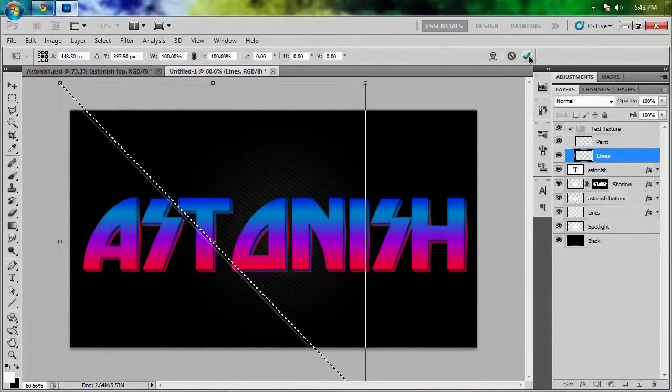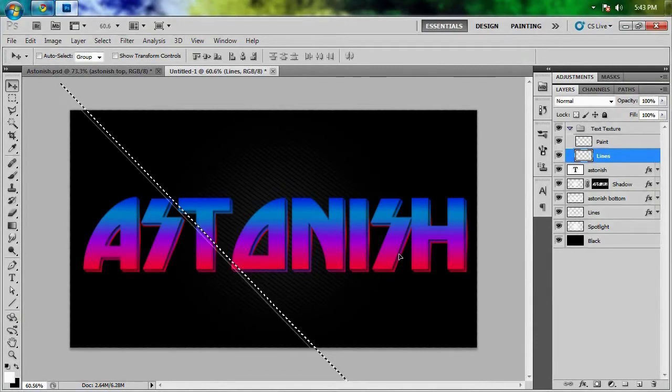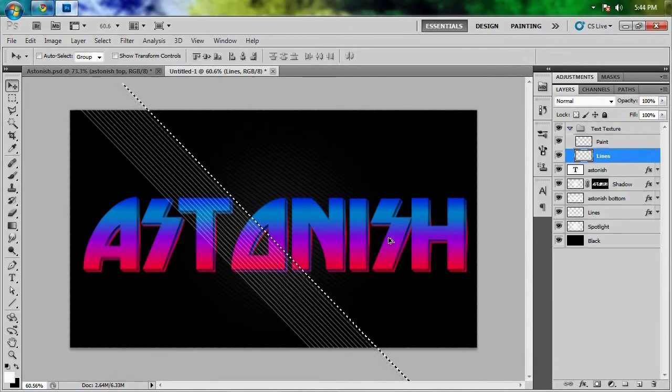So we'll check mark it, and we'll hit Control Alt Shift T to redo the transform we just did, as well as making a duplicate of our line. And we're going to hit that 1 million times.